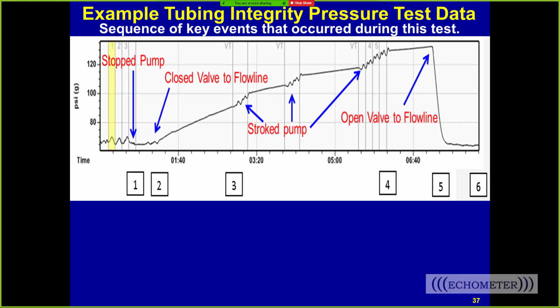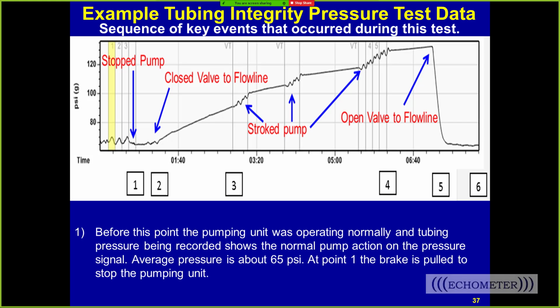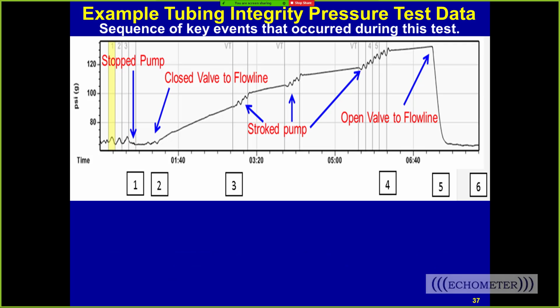Well, one more question is regarding the tubing shots. For tubing shots, should it be better with the well stopped? Yes. That's a good question. When you come to the well, if there's a problem, the well's turned off because there's no production at surface. You go there with your acoustic instrument because someone said there's a problem with this well, I'm not seeing any liquid in the tank. Normally the well's turned off, and that means you can shoot down the tubing because the tubing is not full of liquid, since there's no liquid to the surface.